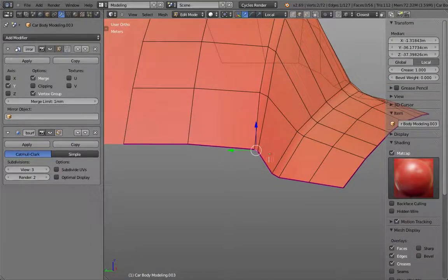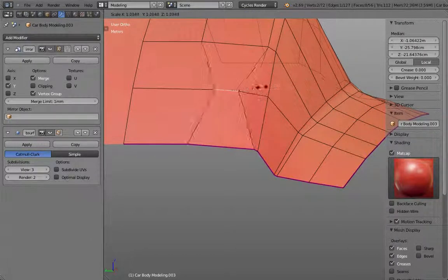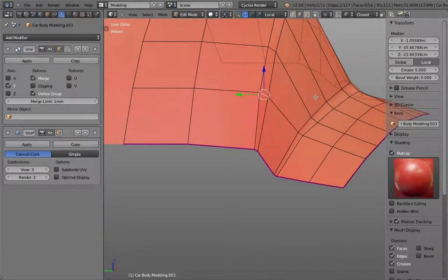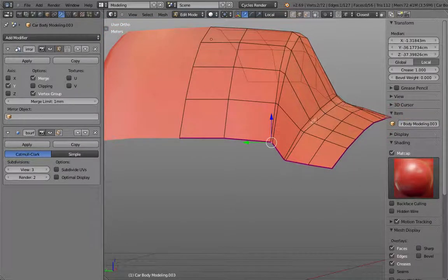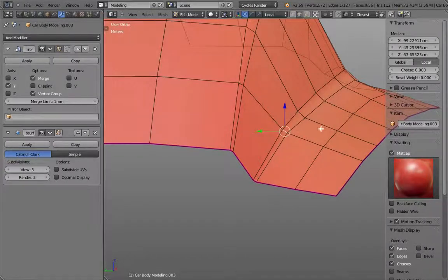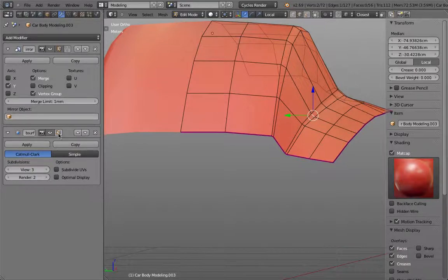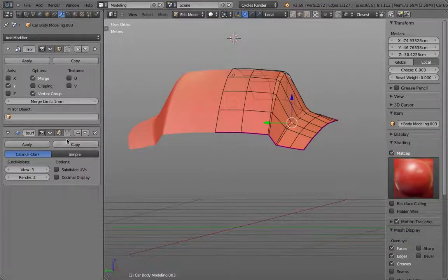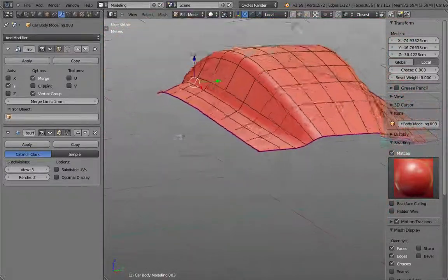Maybe here I scale them together to pinch it more. And I'm only selecting this edge, and when you select an edge and you press scale, you move those two points towards each other. So think about this as playing with the cross section of the fillet. Maybe let's turn on the projection of the editing cage right onto the mesh, and let's take a look.